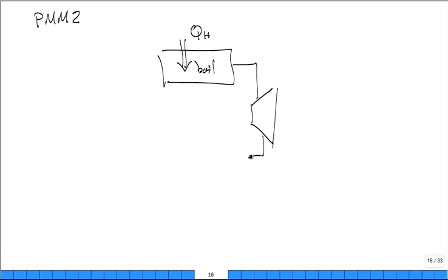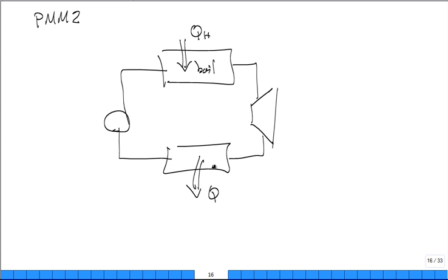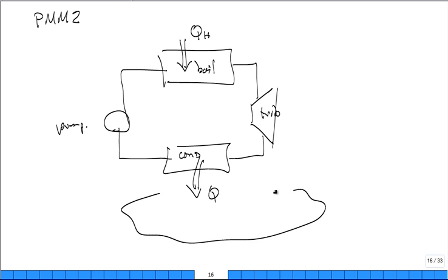And from a steam turbine, typically you put it to a condenser, dump off that heat, and then take it to a pump, and the pump up and over. And so this is the condenser, this is the steam turbine, this is a pump, and this is how we make a lot of electricity in America today. This works. It's rejecting some Q to a lower temperature, let's say lake water or atmosphere. True? Here you're burning coal to make that fireball in a boiler.